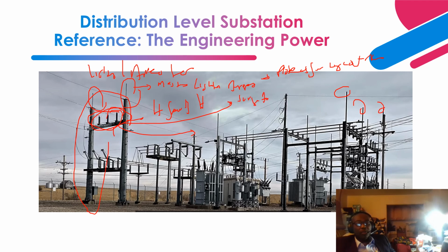It is made of, remember I told you, metal oxide varistors. This is a gapless surge arrestor, and has metal oxide varistors made in the form of discs inside it, and inside it is a fiber insulation layer, and outside is a porcelain or polymer external insulation.